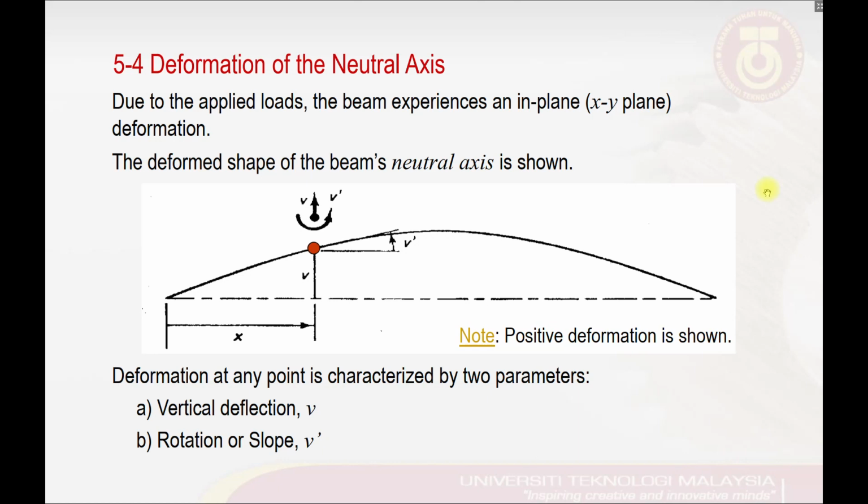Due to the applied loads, the beam experiences an in-plane XY deformation, since we are working in the X and Y directions, so the beam will experience deformation in both directions. The deformation shape of the beam neutral axis is as shown in this figure, where the deflections and also the rotation are shown in the positive deformations.